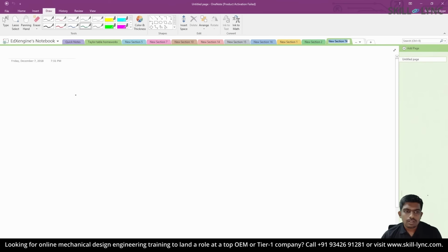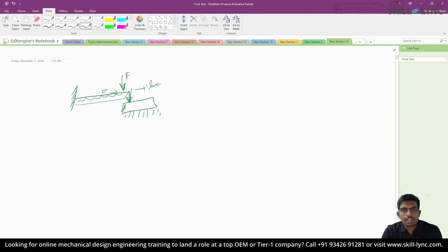For example, if we have a simulation with a cantilever beam, there is a box which lies below the cantilever beam. Now if I apply a force on this cantilever beam, the stress contours on the beam will be linear until it makes contact with the box below it. Once it makes contact with this box, the stress contour on the beam will no more be linear even though it's within the elastic limit. Hence, depending upon the contact status, nonlinearities can step in even though you are well within the elastic limit.